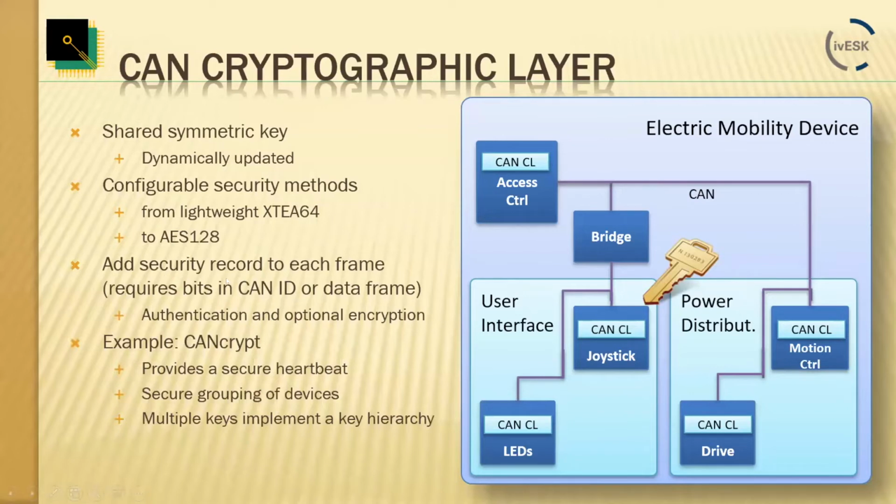Now, most of you will know that there are also the 29-bit identifier CAN IDs. So instead of the 11-bit I mentioned earlier, the frames can have a 29-bit CAN ID. And if an existing system is purely based on 11-bit CAN ID, then by switching to 29-bit CAN ID, we suddenly have 18 bits to play with.